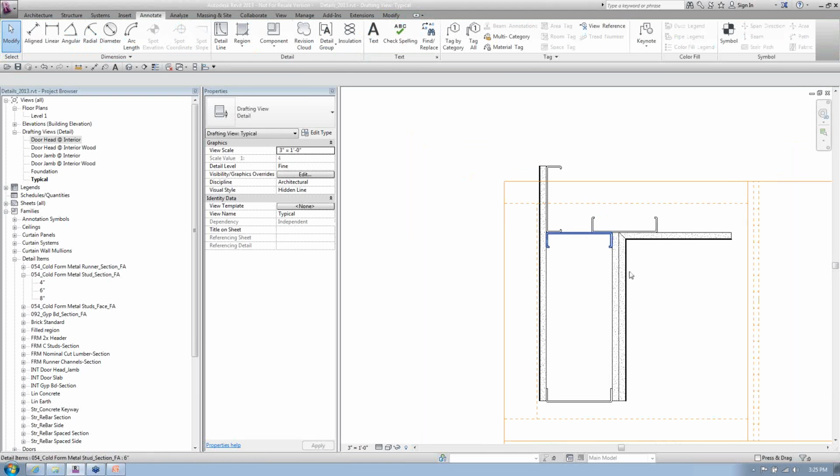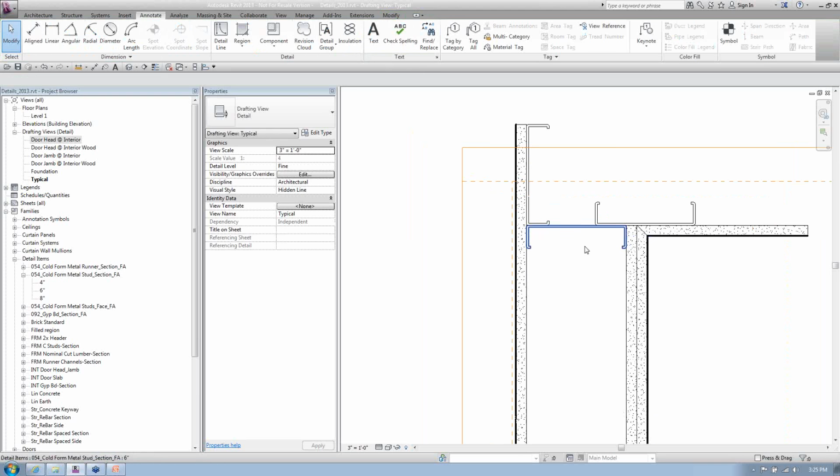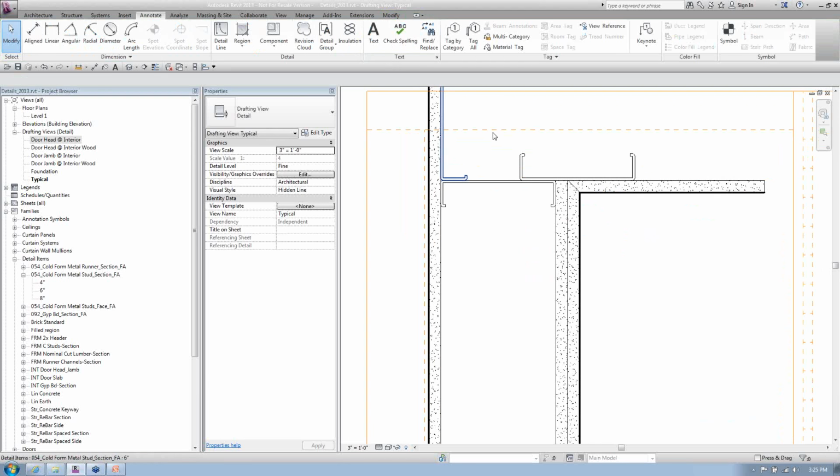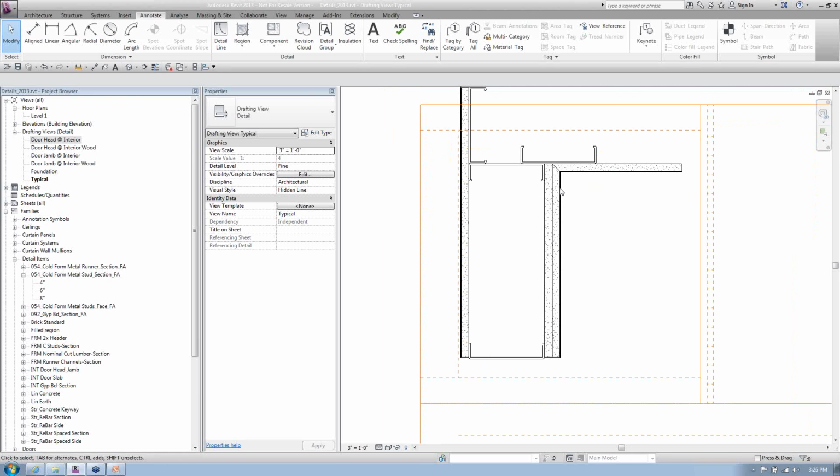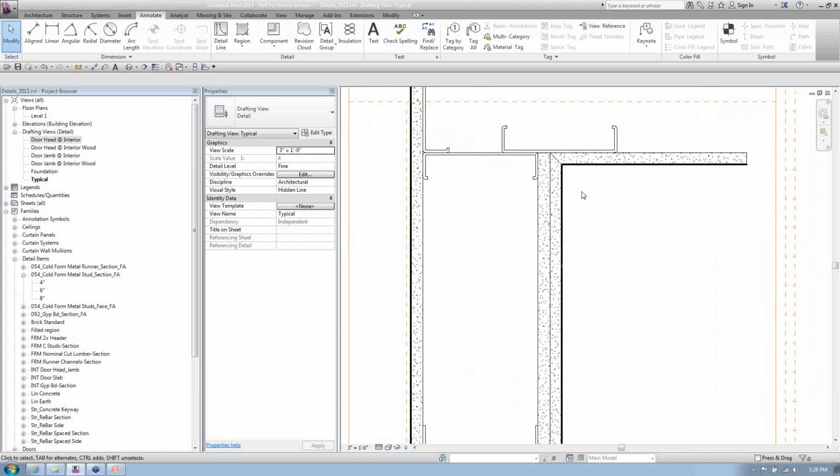It's only going to update as it sees fit. How I accomplished all of that was I used my align command and locked it. I am not a big fan of the align command with modeled components, or even detail components to modeled components, on a hybrid detail. But I am completely okay with aligning and locking things inside of a detail itself.